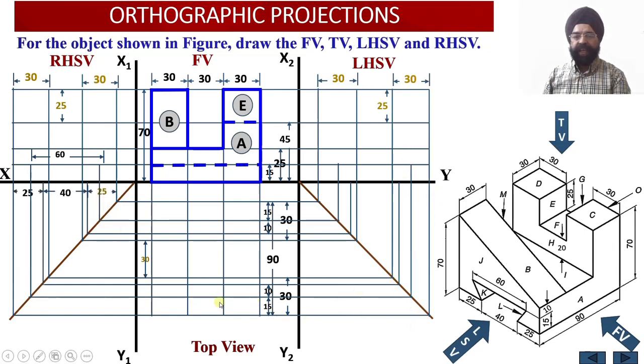Similarly, whichever horizontal projection line was drawn in the top view at a distance of 15 millimeter from the front face, on that particular line I am going to locate over here the point which is lying at a distance of 15 millimeter from the base. That is, this point of the angular slot on the front side will be located.